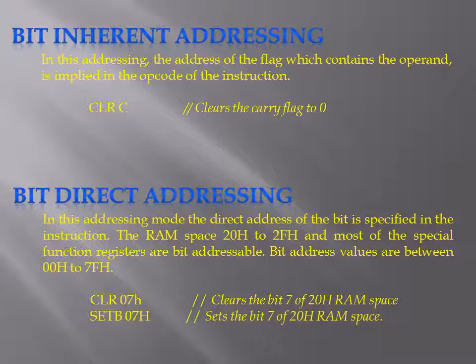All 4 ports make 32 individual bits, and those bits can be programmed individually as a single bit. Every bit has a number. If we give the number of the bit, a particular bit will be set or reset. That's called bit direct addressing.